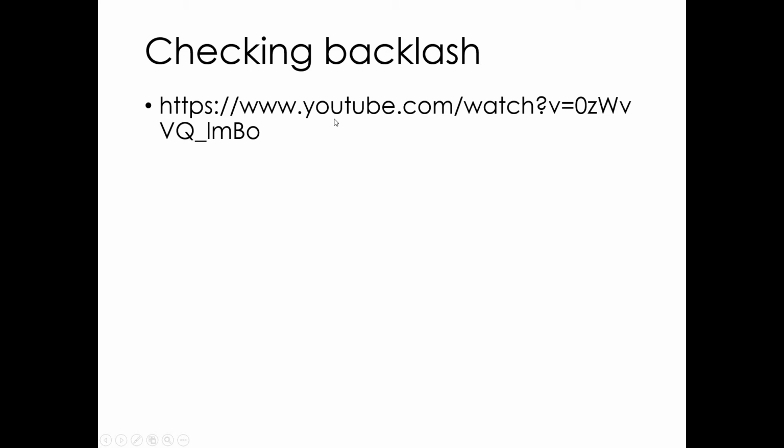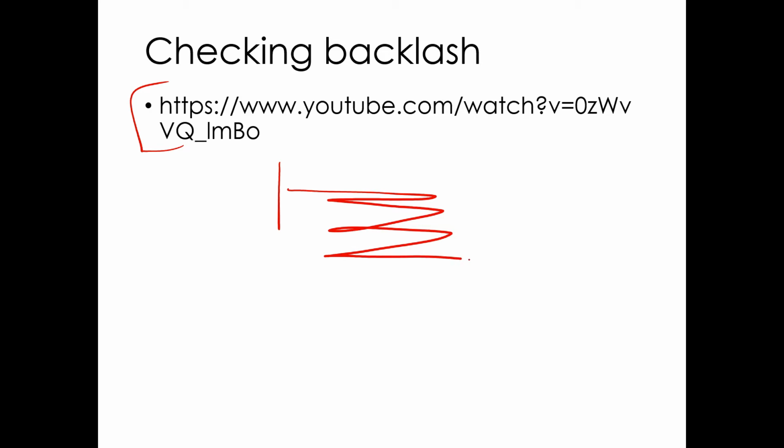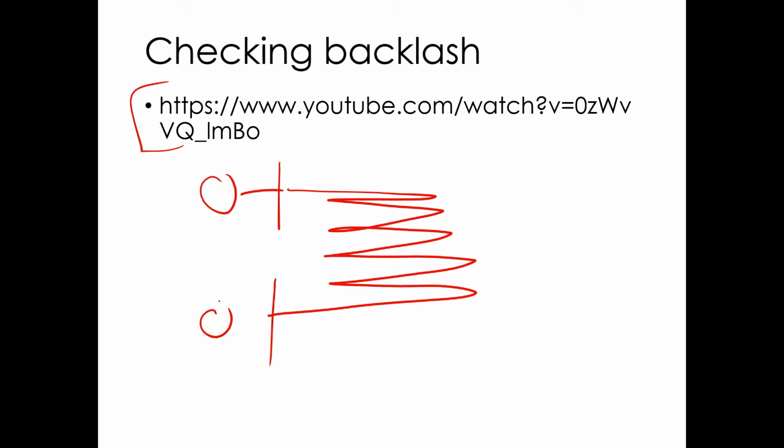Checking backlash. This is a video of someone with a homemade CNC router trying to measure backlash. And one mistake they make in this video is they go back and forth and back and forth, and then back to the original position, and with a dial indicator measure the delta. And it ends up right back where it was. Well, that's not checking backlash. So in backlash, you need to go this way, and then you need to reverse, and see where you're at after one reversal.